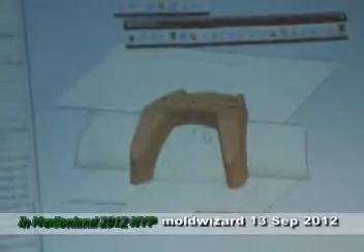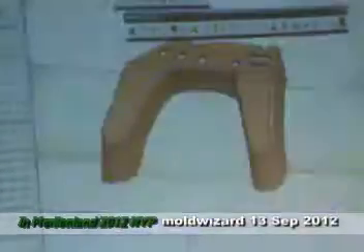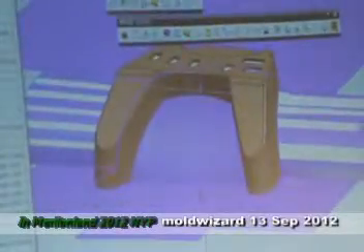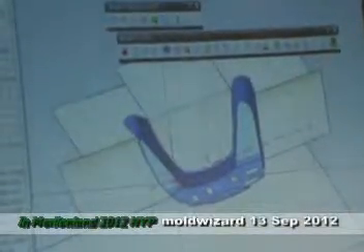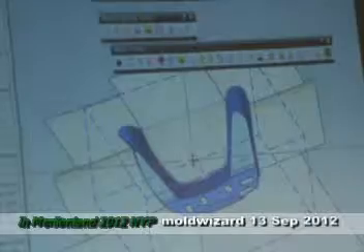According to our experience, this kind of parting surface will be better than the previous one. That's why I changed to this kind of shape. Because the insert will be quite solid with this kind of parting.